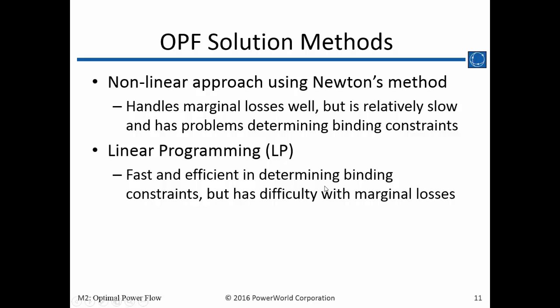As we'll see when we look at linear programming and how the software actually solves it, there could potentially be thousands and thousands of constraints. You know, every transmission line could be something that could be loaded, but practically speaking, there's usually just a handful of elements that end up being congested or run to their limits, and the linear programming software is good at ignoring the ones that aren't needed.